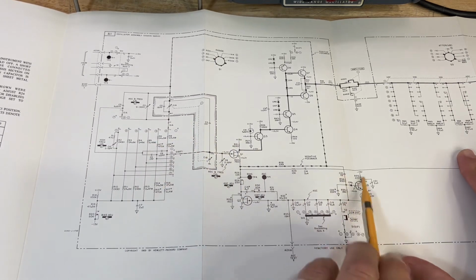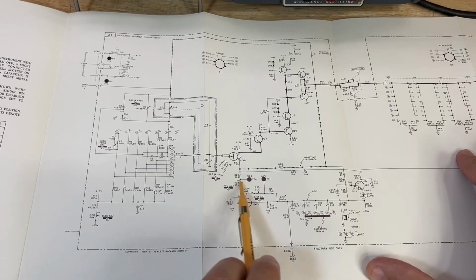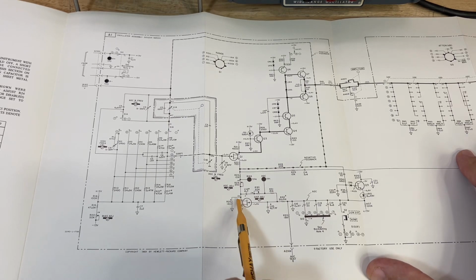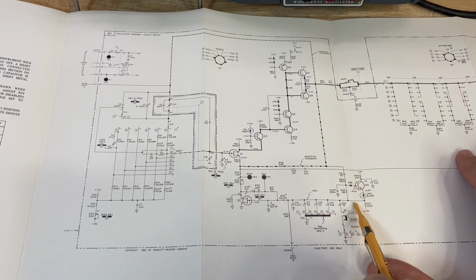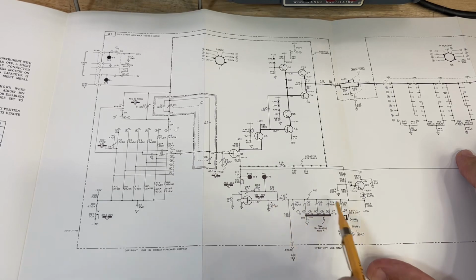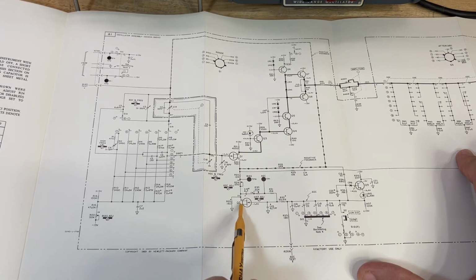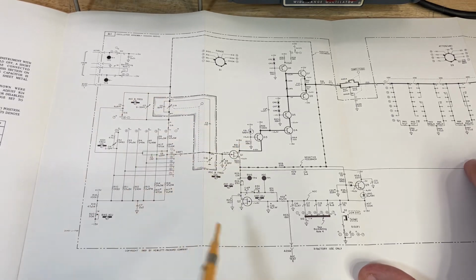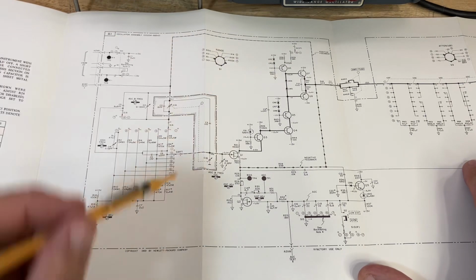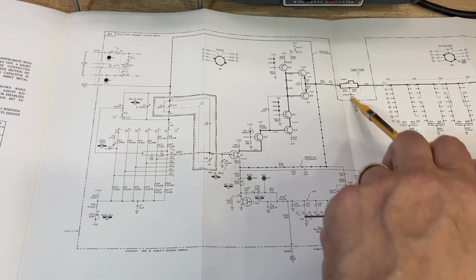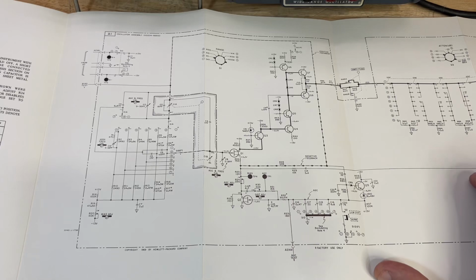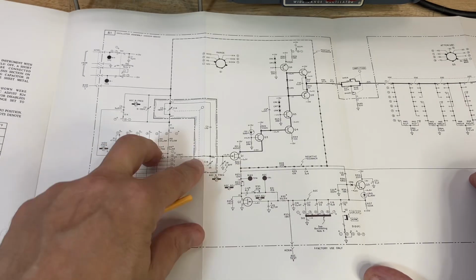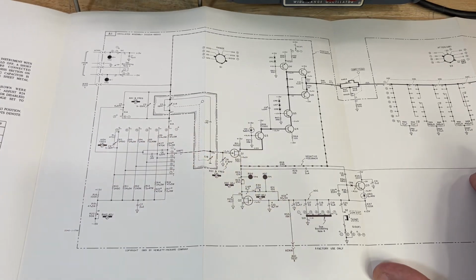So it's a far more complicated circuit. To replace the light bulb, they use a FET and a bunch of other envelope detection circuitry and some low pass filtering so that we can provide the negative feedback for amplitude control as well as minimizing distortion. There's an output attenuator and so on and so forth. So that's the 204C circuit.